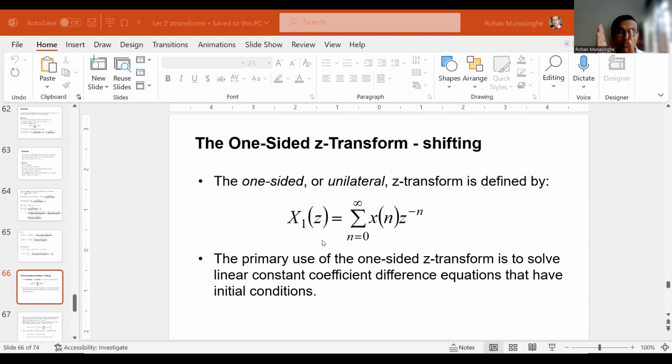If it is just one step shift, you need to put the initial value there. We call it initial conditions. You have heard that in many applications, initial conditions, or boundary conditions. And if you shift by 2 steps or 3 steps, n number of steps, you are creating that many spaces, and you have to introduce these samples before you can actually have a complete transform of the sequence. So this is what we are going to look at next.